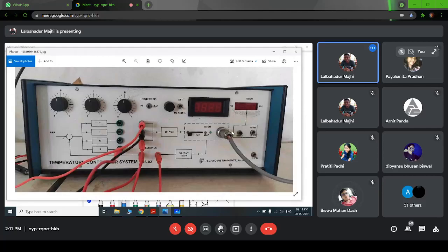Yes sir. So the output is now about 10 degrees Celsius, right? But our requirement is 24. So now this temperature sensor will sense that the output is 10 degrees. It will give feedback to this summing point, right? So now what is the error? The error will be plus 14 degrees, right? Now this error will be given to the driver for our normal closed loop system, okay?